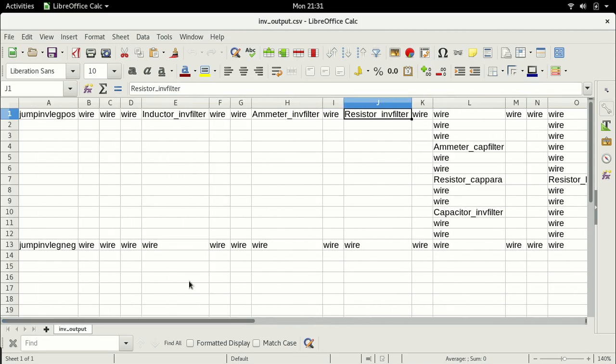So what is this inductor capacitor? This inductor capacitor is the filter at the output of the inverter. An inductor itself forms a filter, a capacitor itself forms a filter, and their combination forms a second order filter. A second order filter means it has double the filtering capability of a normal filter. Now I'm not going to go into mathematics.